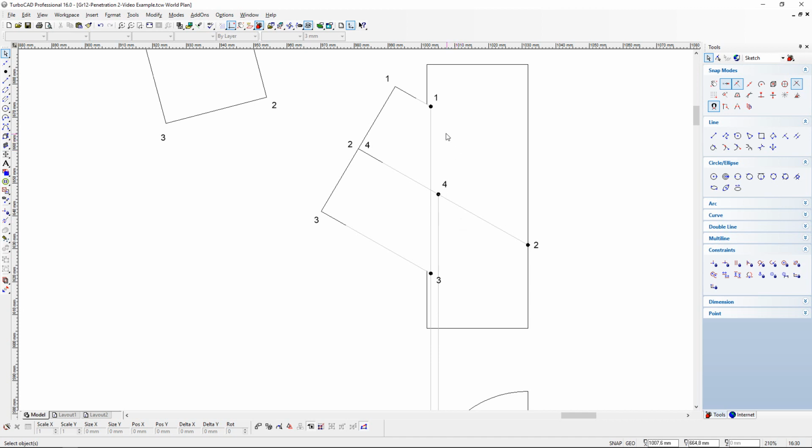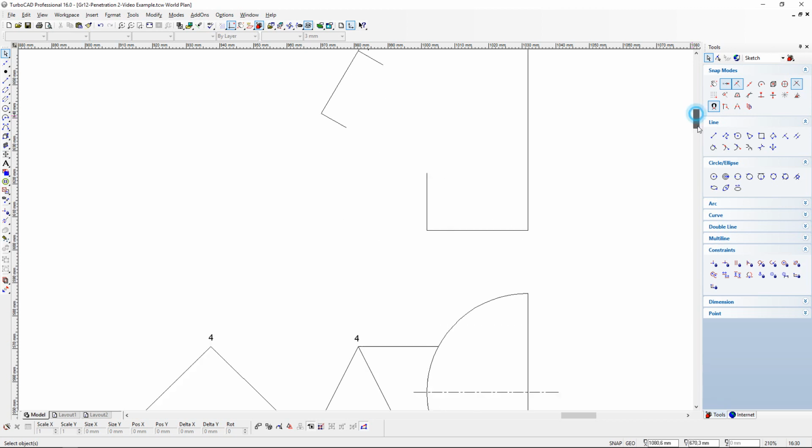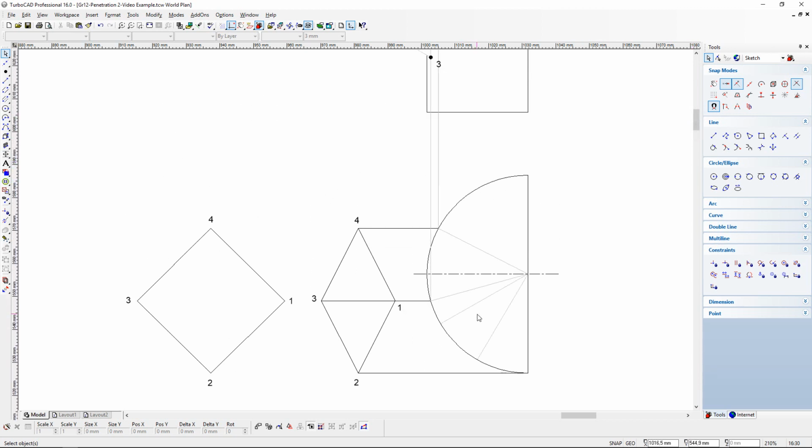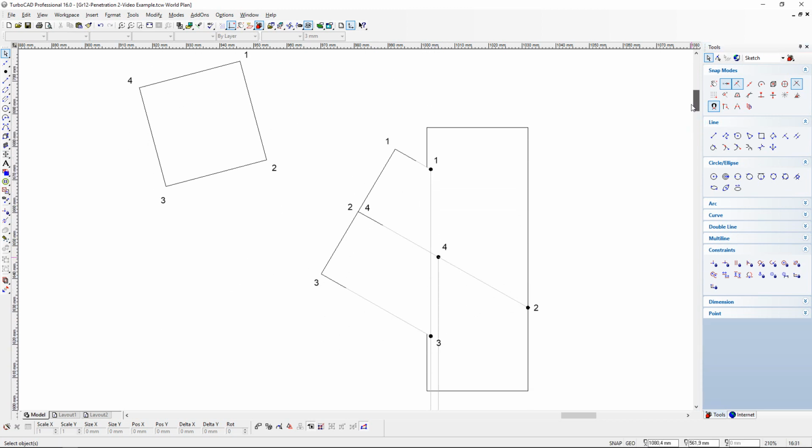Okay. So what we need to do now is to determine the profile of the curve from each one of the corners, number 1 to 2, 2 to 3, and then to 4, and back again to number 1. But we can't draw a solid straight line from number 1 to 2 and all the other corners, because this is a curved surface. On our top here, we obviously see that it's a half cylinder. So whenever a straight prism interacts with a round surface, we will have a round profile in our answer.